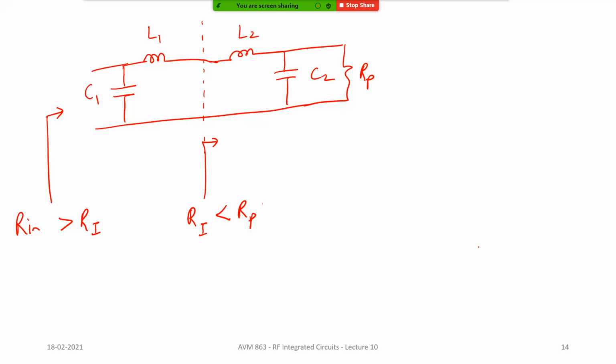So if I reduce the gate width, W decreases, and so the flicker noise will increase. But on the other hand, if I decrease the width of the gate, the RG resistance, which is spread over the gate width, will also decrease. If the number of resistances decreases, the ultimate noise generated by the gate resistance will also decrease. So these two, aren't they contradicting each other? On one case it is decreasing, and in the other case it is increasing.